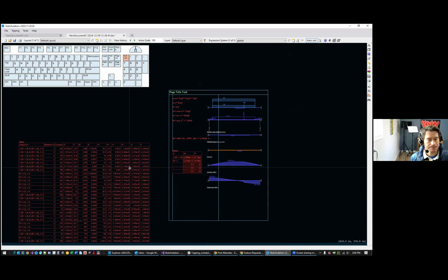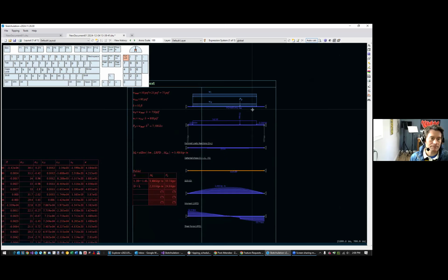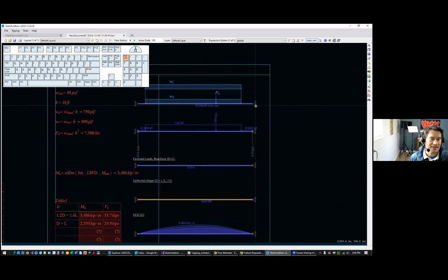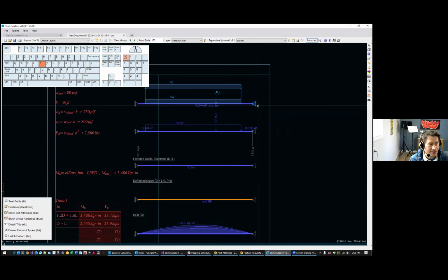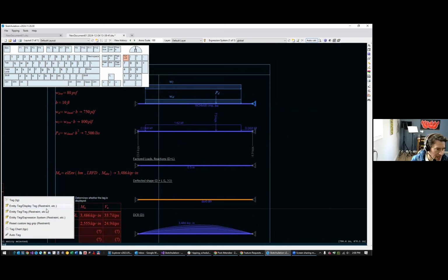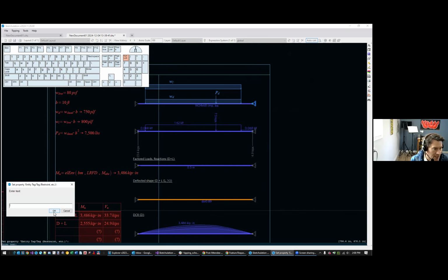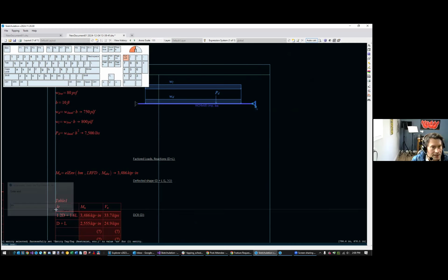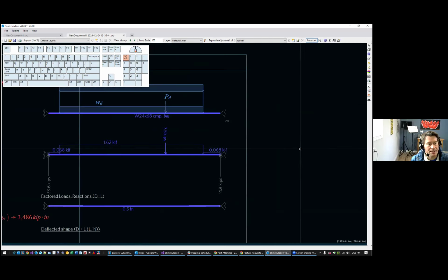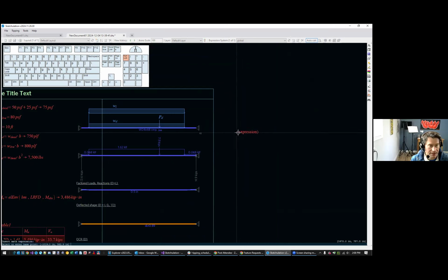I just had a quick question. I'm assuming you can link loads, like if you had a second beam element and you made that be like a reaction from your other beam. And it would all update. Yeah. So the way you would do that is you would tag this restraint, and I can just give that say RS like that, and so now it has a tag.